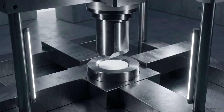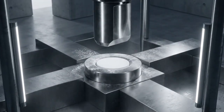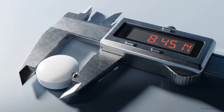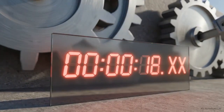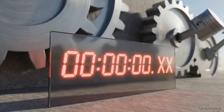Let's pull this out of the abstract and look at a physical tablet compression machine operating at high speed. For these specific pills, the target profile demands a precise dissolution rate, so the drug absorbs into the bloodstream on time. That means the measurable quality attributes are the exact hardness of the tablet and how many seconds it takes to disintegrate. To guarantee that hardness, the mechanical inputs must be flawless. The process parameters are strictly set to apply a highly specific compression force, perfectly timed with the exact granulation duration.